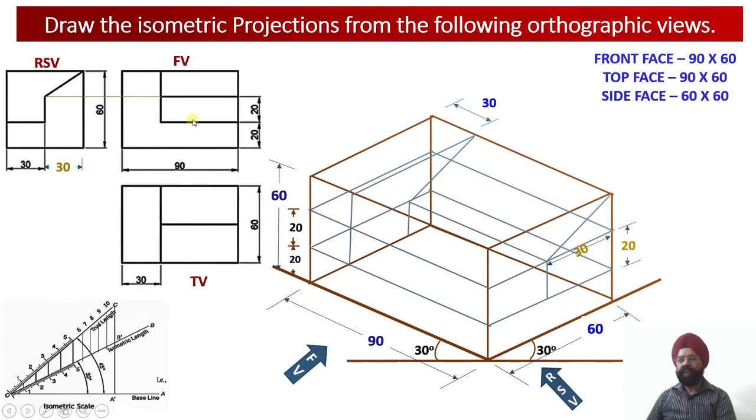Now my third element I have started with. This is my third element. I am going to draw a vertical projection equal to 20 millimeter. So from this surface, 20 millimeter down, you can see it is meeting at this particular ring which is at a distance of 20 millimeter from the base. Once you join this face, this is my vertical face, which is visible to me in the front view. So this vertical face has also been generated.